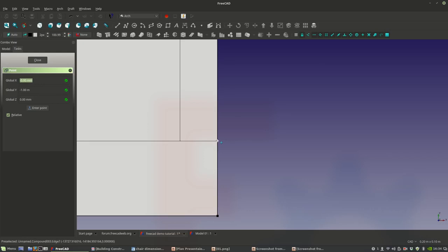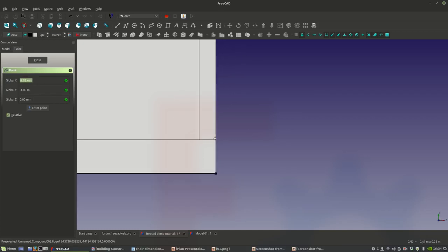So now I can see that I have this extension that keeps popping up. I don't want it to show up. I have this equal thing. I don't want it to show up. And then I have this perpendicular. Is it the perpendicular or the plus? So this is this guy. It's the ortho. I don't want him to show up. Okay.